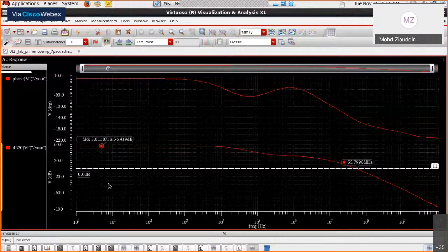And one more doubt, sir. While designing the common source amplifier, while doing characterization, we fixed the VDS to 1.65, which was half of 3.3. But while doing the op-amp MOS characterization, what VDS was used there? Same. Actually, we have used the same set of curves. But again, during operation, the tail current and the active NMOS device will have a different overdrive. It is not about the overdrive.